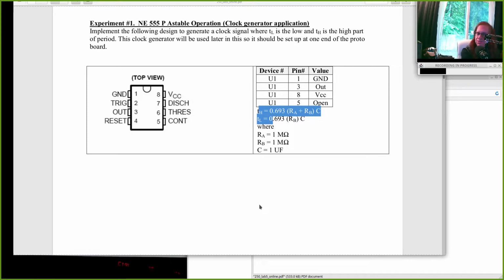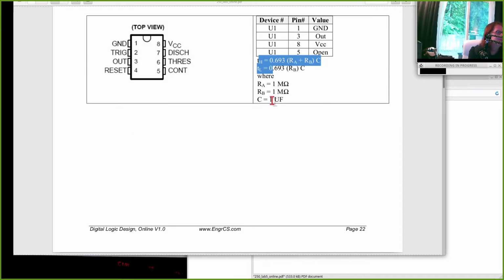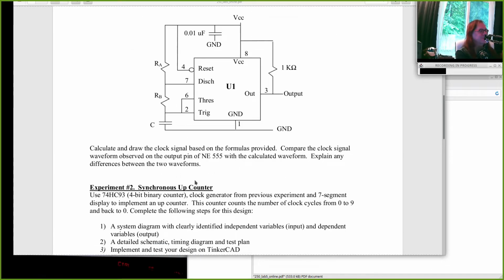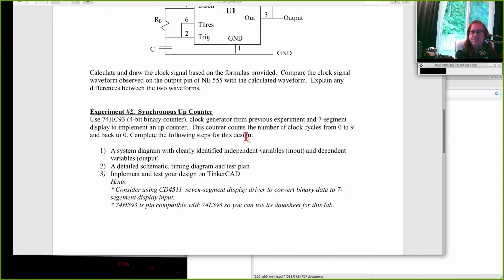So below micro is nano, so 1,000 nanofarads would be the same as a microfarad. So if you made this 250 nanofarads, it would run 4 times as fast. It would take about half a second to go high and then low. And you can do quicker debugging, for example, with your counter circuit in the past lab.